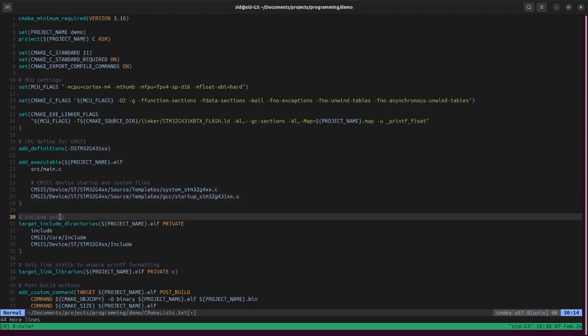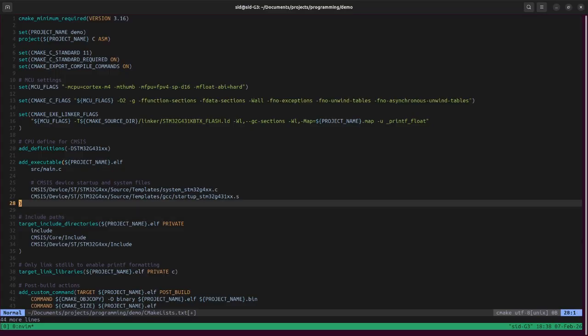Yeah, so make sure that you add those. If you copy the code from the code generator, it will be added for you, provided you copied exactly your Simpsons folder and pasted it in your project. One thing you should watch out for is this line here, because this is also dependent on the microcontroller you're using. So if you are working with an F1, it will most probably be F1 here instead of G4. So F1 instead of G4.